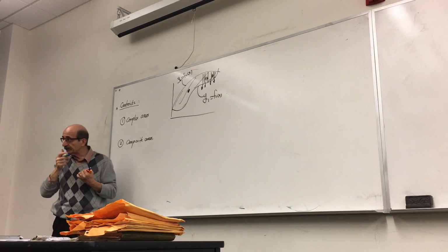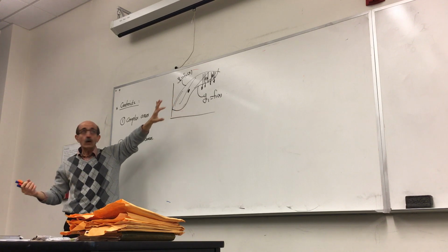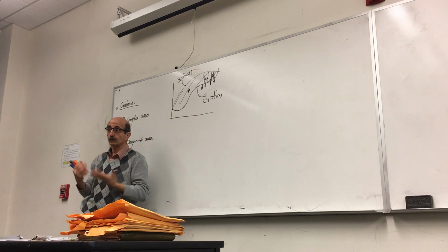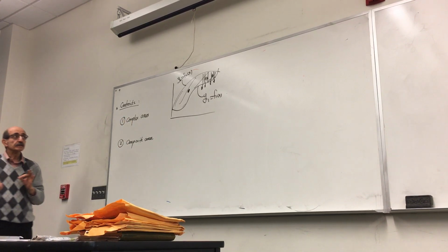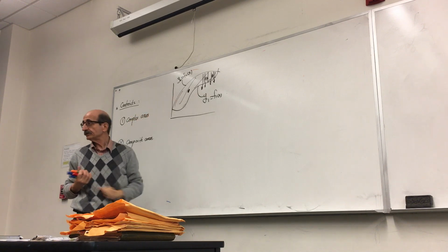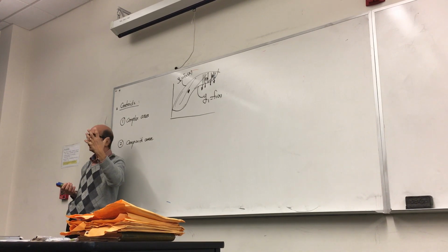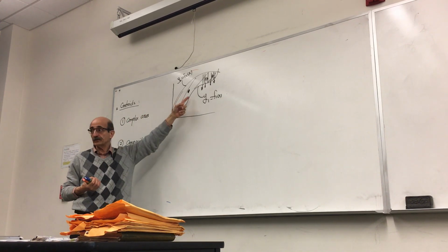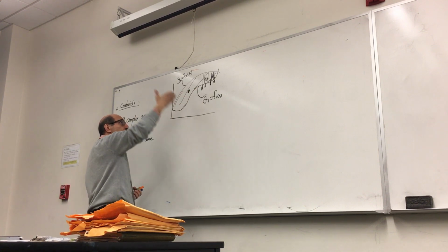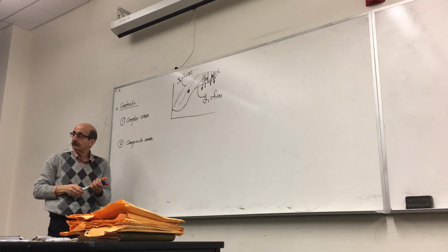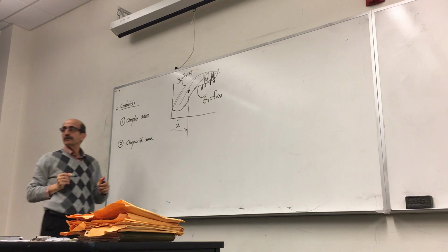The objective of finding a centroid is to find a location where you can move all these forces, which is a total dA, or total area, but by moving that to that point, there is no moment that you should put there. In other words, from the concept of equivalent systems, what does that mean? That means you find this location in such a way that the moment of all these forces would be zero. And then that will give you this distance, which we call that x bar.